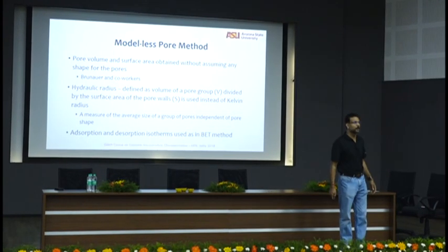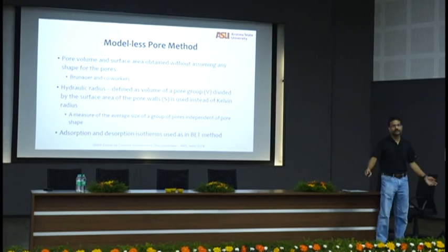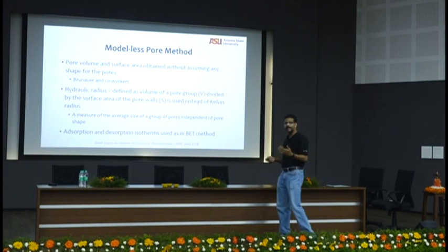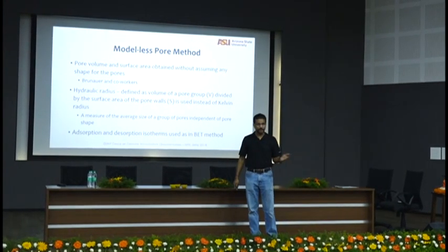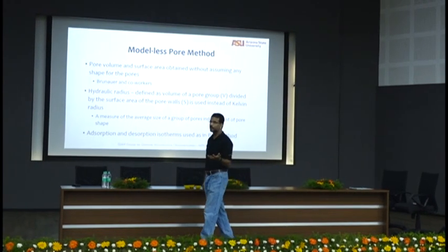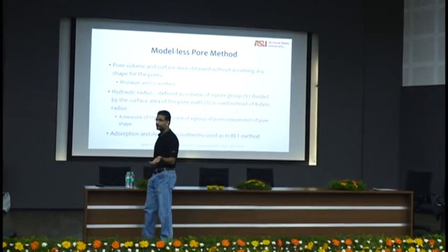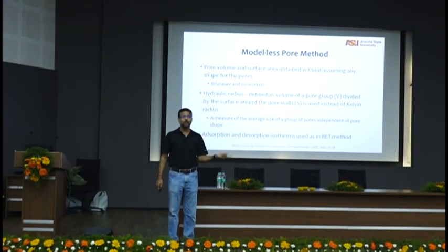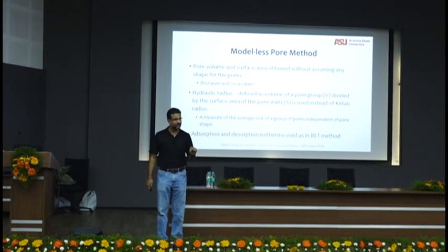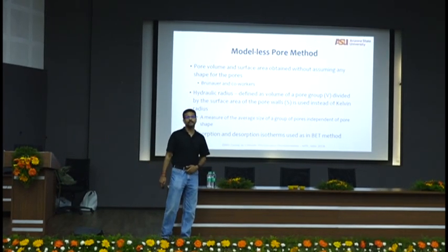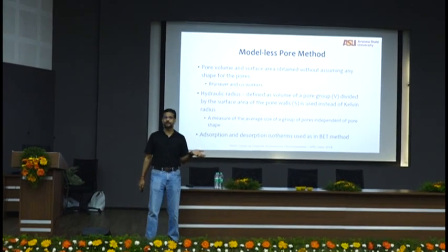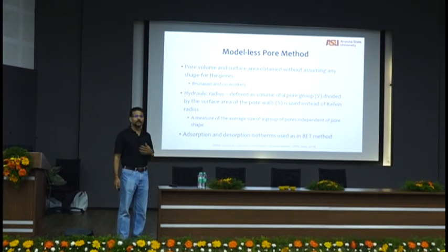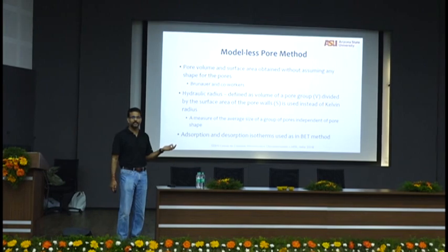But again, in our business, we oversimplify with something like compressive strength. That's the price we are paying sometimes for oversimplification. Because the whole idea was, the guy in the field should know. Yes, the guy in the field should know, and you are not going to teach him cement chemistry for sure. But the technique that he uses should be relatable to what you used to design that material. If you can tweak it whichever way you want, then we will end up with all the quality control problems that we have: the field is doing one thing, the lab is doing another. There's always a fight between the contractor, the engineer, and the client.